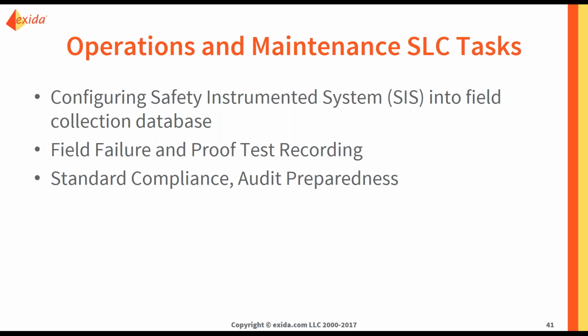The idea here is that you want to validate your design and analysis from earlier on in the life cycle. So some failure rates were assumed, initiating event frequencies, probability of failures. All of this is great data, but it's never as good as your actual site data. And so you want to collect any field failures. You want to be able to use that to validate your design and also in future analysis. And so you're going to have that one database. You're going to have to configure your entire site into that database. Then you're going to have to perform the field failure and proof test recording. And you may have to prove standard compliance and be prepared for an audit at some point.